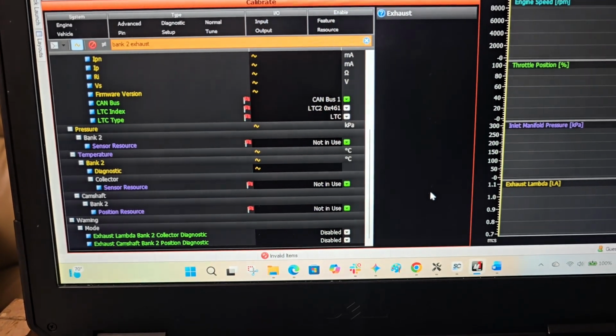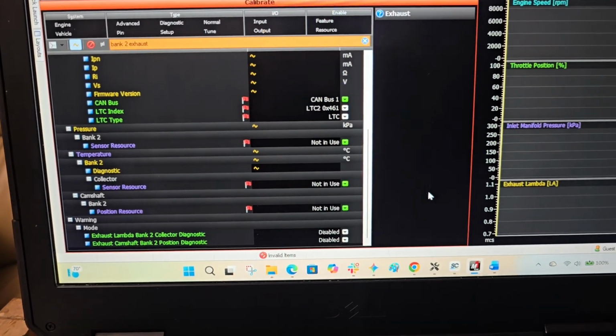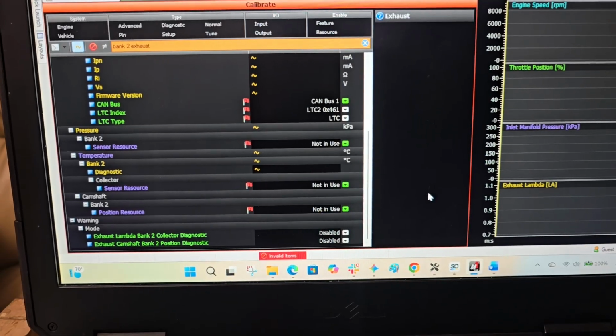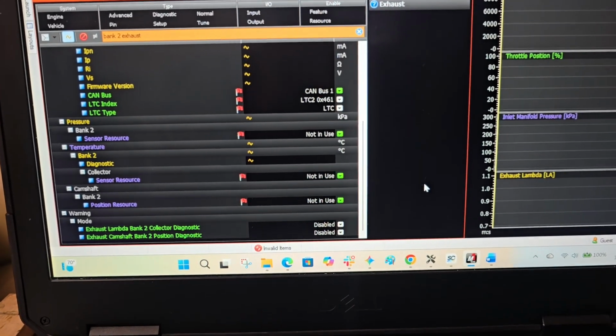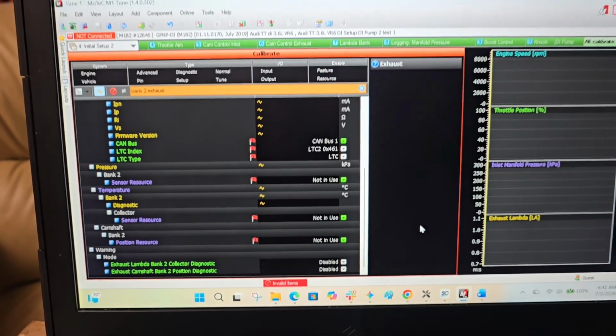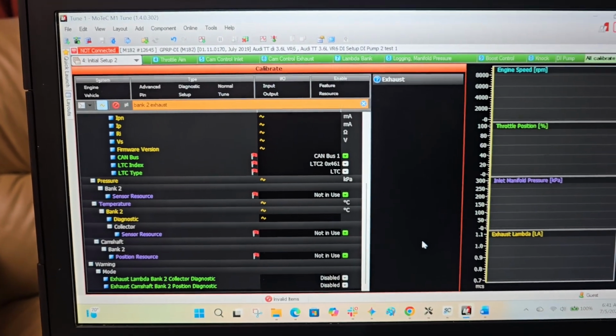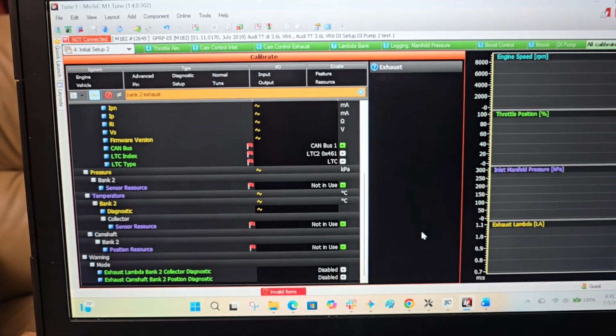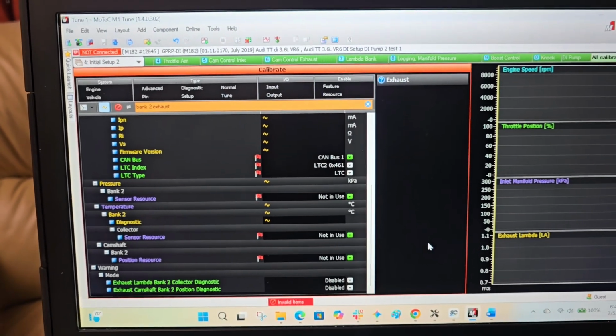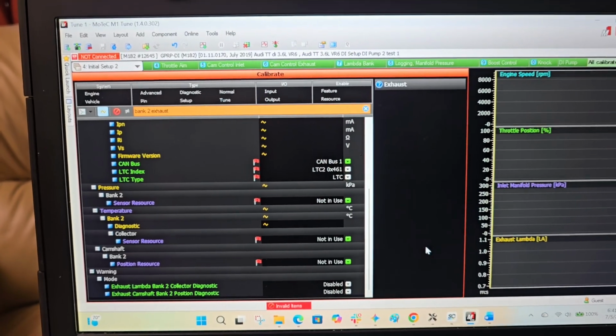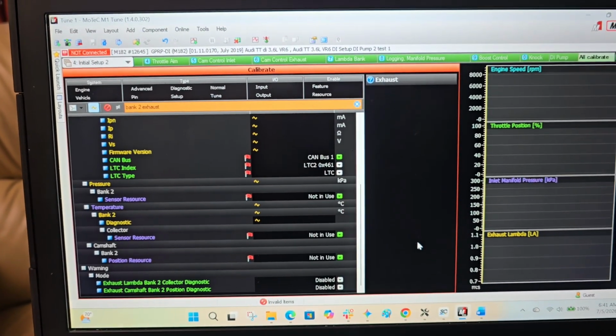So throughout that combustion cycle, we actuate the pump 3 times, and I measured that profile for lift as well as base circle throughout each step on a degree wheel, and that worked out great.